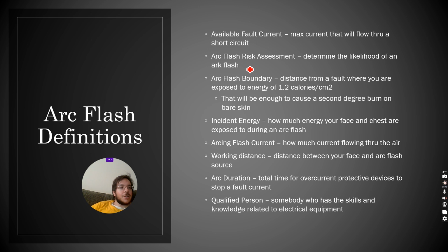And we can't get rid of the arc flash hazard completely, even in an industrial facility. Something as simple as racking or turning on a breaker in the room, or even doing nothing, you can still have that hazard. So my recommendation is always to have, especially, there's a lot of robotic systems now, and Eaton has a system that can suppress an arc flash in a main switchgear. It's something that people should look at, for example. But yeah, there's ways to reduce the risk significantly, but there's no way to eliminate it.